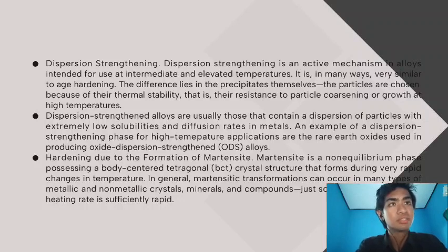The basic mechanism of martensite formation involves the simultaneous rearrangement of many atoms, where a series of individual atoms move a distance less than one interatomic spacing. This small but orderly movement of many atoms changes the lattice structure of atoms into a BCT crystal structure.